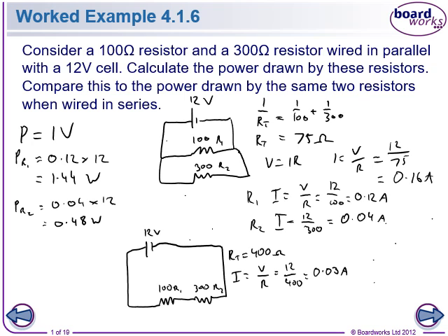All right. It's actually a good problem. There's a lot to it. All right, so next, we need to work out the voltage going through each resistor. Because remember, our voltage is different in each resistor in a series circuit. So our voltage for R1 is equal to IR. We know our current, because our current is the same the whole way through.